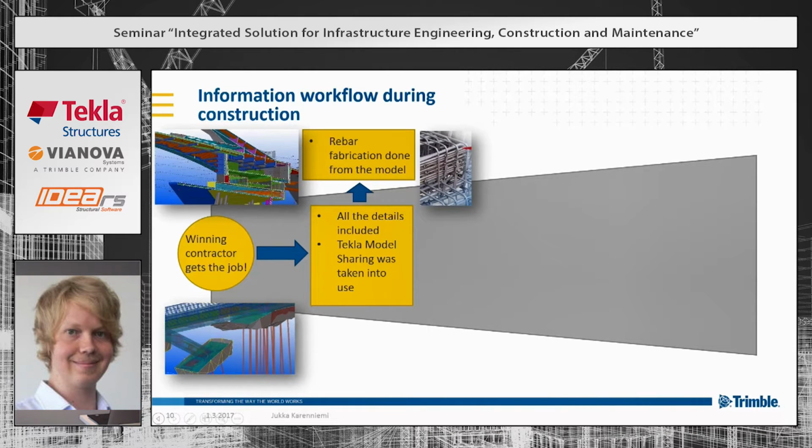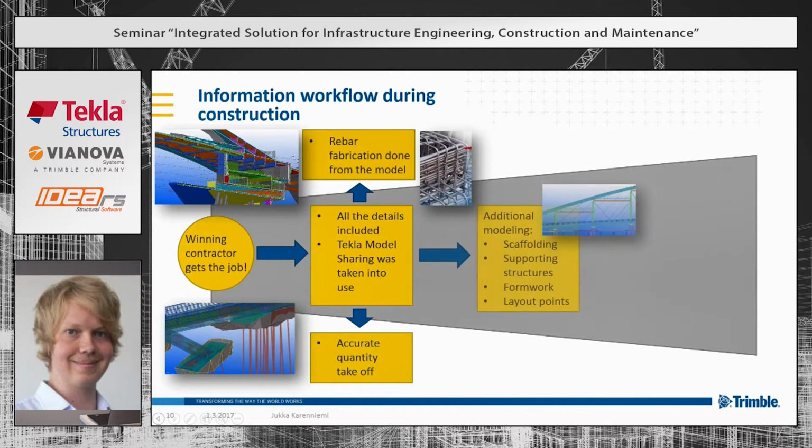Rebar fabrication could be done from the model, and really accurate quantity takeoffs. In addition, the contractor used the model to get information like the quantities and the rebar information and fabrication information. The contractor also used the model for additional modeling. They modeled scaffolding, supporting structures, formwork and layout points directly into the model.